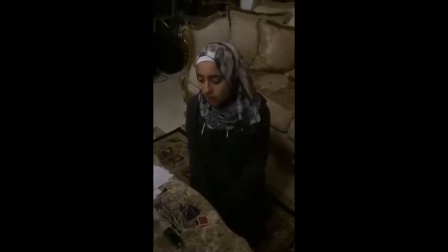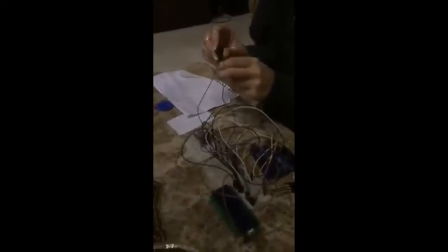Hello, I'm Sra Atif. I'm a 37 engineering student. I'm gonna explain to you about the hardware of our project. First thing, we have the buzzer. Its negative wire is connected to the ground. Its positive wire is connected to one of the legs of the resistor. The other wire is connected to pin number A2.